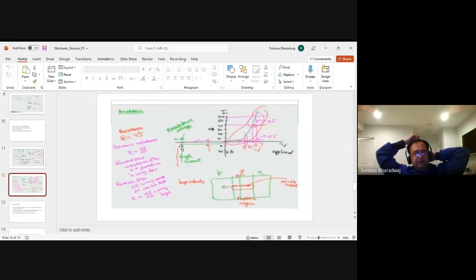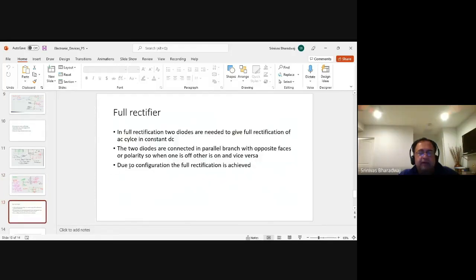A diode which operates in that range of avalanche breakdown is called a Zener diode. It is just a regular diode, I think, or specially made slightly differently, which operates in that avalanche condition. It's not usually thought about, but you must know about these things if you want to do well. Now, in full wave rectification, you have two paths.